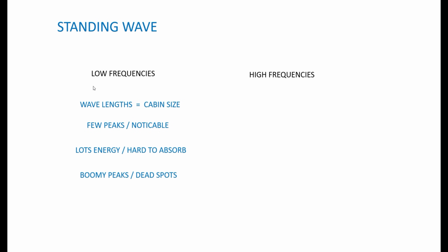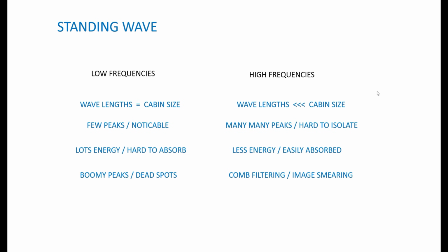That energy, there's a lot of energy, it's hard to absorb by the seats and the carpets and the headliner and all that type of stuff, right? And so you get this traditional standing wave phenomenon of acoustics where in some points in the car the bass is very boomy where it's adding up, and some points we have dead spots in the bass response. Now compare that to high frequencies, things from your mid-range and your tweeters, 500 hertz and up.